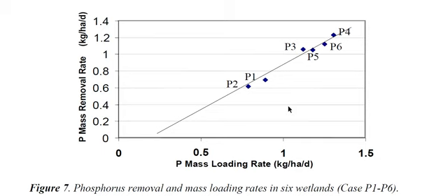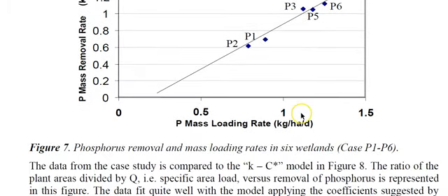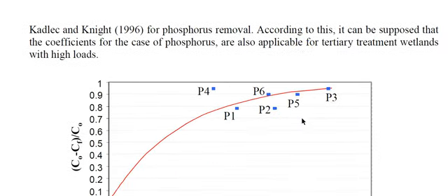So what it really means is that if you used a standard wetland design, which is just taking a septic tank and then a wetland, while we put the bioreactor in between, that way you can shrink your wetland by maybe 90%. And that can make it possible to build in many places. For instance, in these cases we look at here, they were just in the backyard, under the lawn of the house on these farms. Doesn't take up much space at all. And it seems more stable. So that was, I think, the most important part.